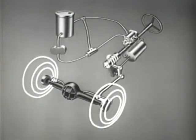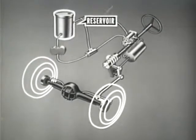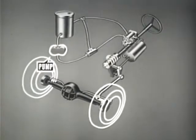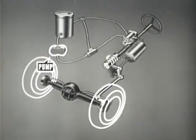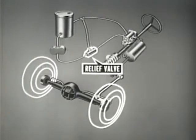Now let us review the operation of the hydraulic steering system. The reservoir supplies fluid. The pump, driven by the engine, delivers the fluid under pressure through the relief valve to the control valve. The relief valve provides an escape for excess pressure back to the reservoir.